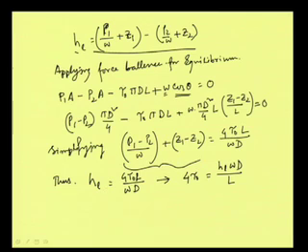Well, now this 4 tau 0 means we are writing about the shear stress. This tau 0 is coming from the property of the surface of the pipe and then other properties of the fluid, a combined effect, which is basically influencing the entire resistance. So, this is giving that resistance property, and as we discussed earlier, this resistance depends on the square of the velocity in turbulent flow.